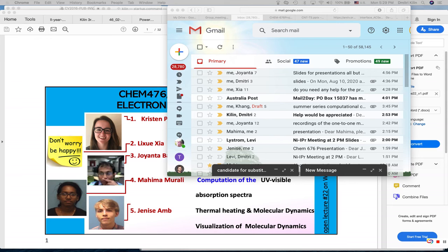The second part is about the electronic relaxation, which is just about the electronic convergence. In this part, I usually change NELM, which means the maximum number of steps of the electronic convergence. If we are dealing with a system with a bad initial structure, this could help us to get convergence in electronic relaxation.